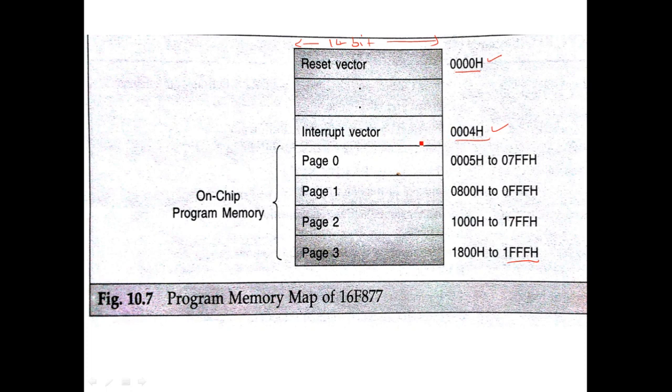Here you have to check which type of interrupt has occurred, because different interrupts have different flags. Okay, interrupt flags. So whenever an interrupt occurs, that particular flag is set. So here you can write a program at this particular address to check the flags, and depending upon which flag is set, you can understand which interrupt has occurred, and depending upon that, the execution can be transferred to the corresponding ISR. So that's how this single interrupt vector works.